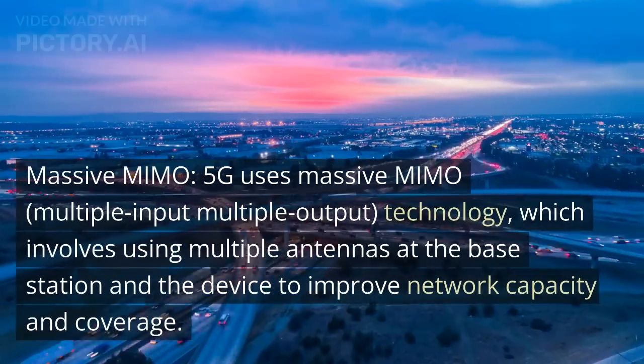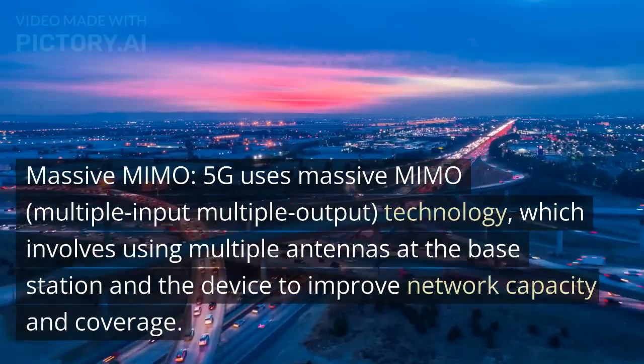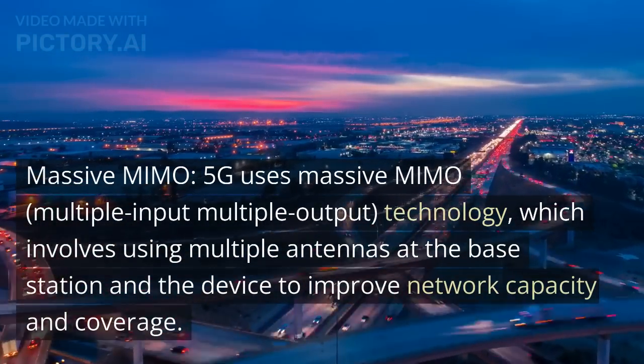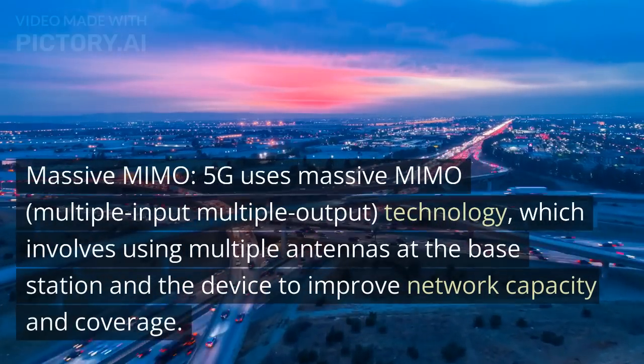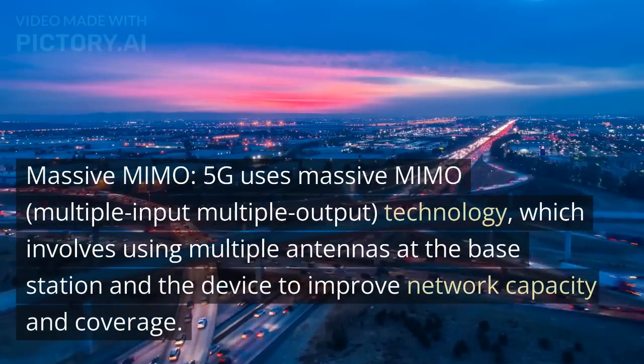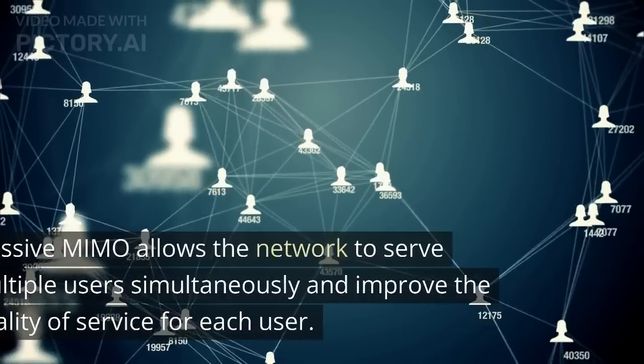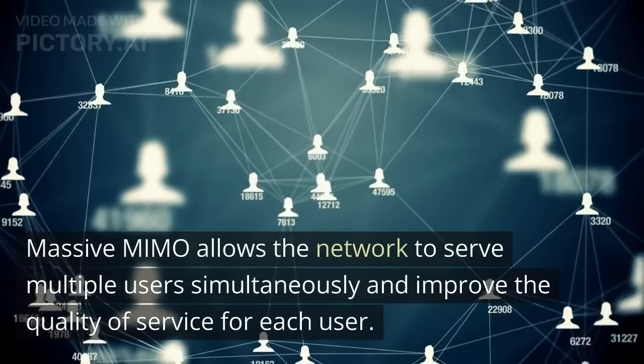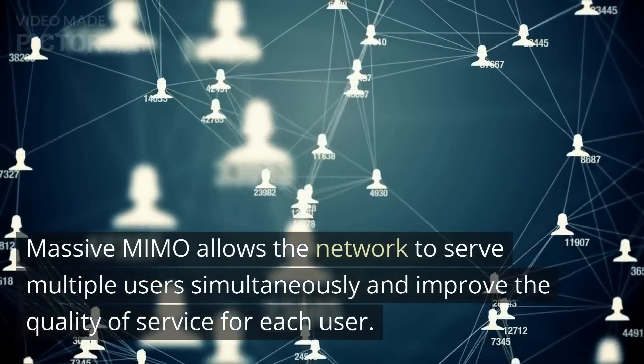Massive MIMO. 5G uses massive MIMO, multiple input multiple output, technology, which involves using multiple antennas at the base station and the device to improve network capacity and coverage. Massive MIMO allows the network to serve multiple users simultaneously and improve the quality of service for each user.